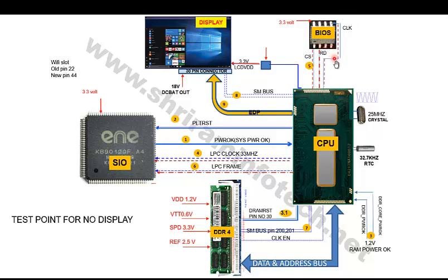When flashing the BIOS, you have to make sure your model number and version number are the same. Sometimes the mistake we make is putting the same BIOS but with a different version. In that case your display won't appear, so you have to make sure of that. Another thing is, in newer generation motherboards, there is the CSME, the Converged Security Manageability Engine.